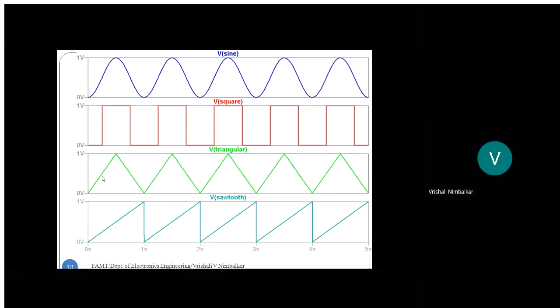Right? Now we will look into the triangular waveform. In a triangular waveform, what should I do? I should keep on sequentially sending the digital values 0, 1, 2, 3, which get converted into analog signals. I keep on incrementing till it reaches FF, and once it reaches FF, I will gradually decrement. I will not decrement suddenly, because that sudden decrement gives me a ramp.